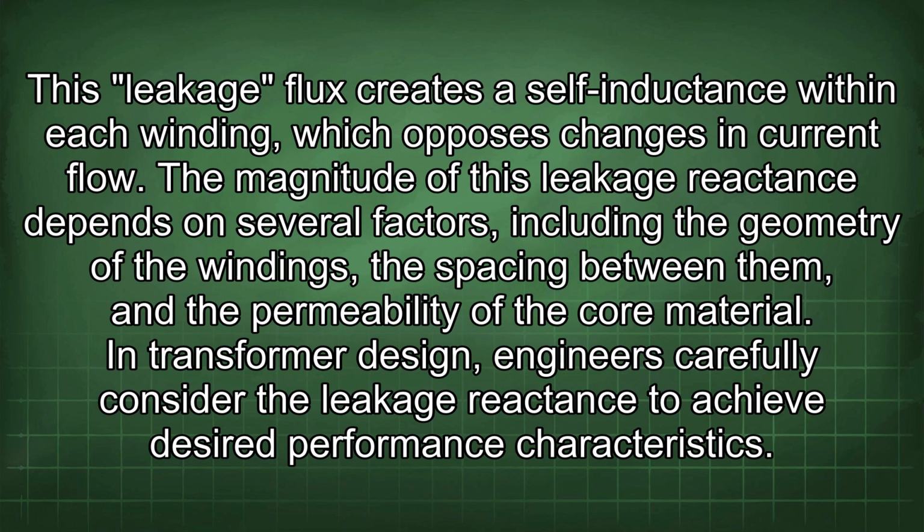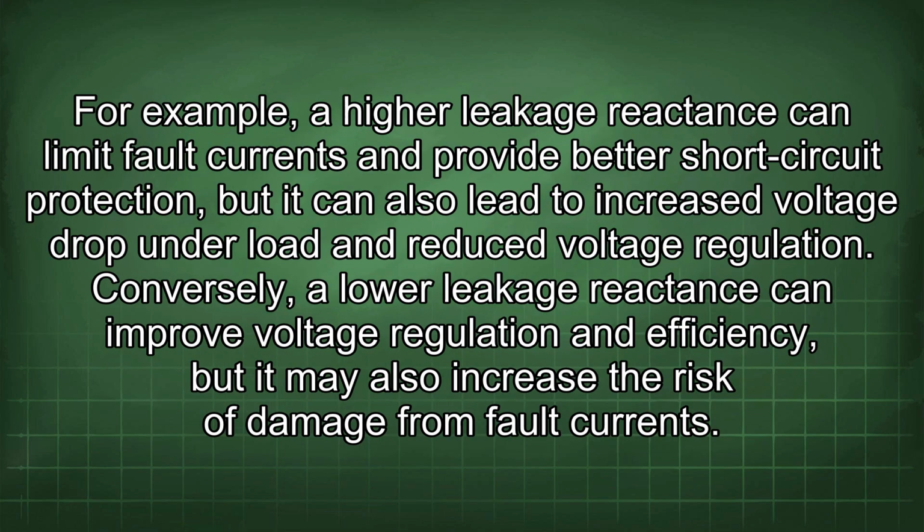In transformer design, engineers carefully consider the leakage reactance to achieve desired performance characteristics. For example, a higher leakage reactance can limit fault currents and provide better short-circuit protection, but it can also lead to increased voltage drop under load and reduced voltage regulation. Conversely, a lower leakage reactance can improve voltage regulation and efficiency, but it may also increase the risk of damage